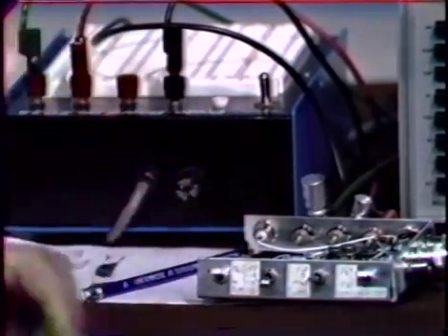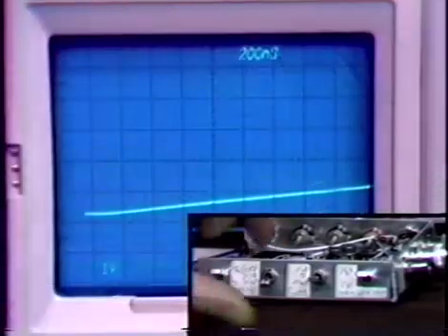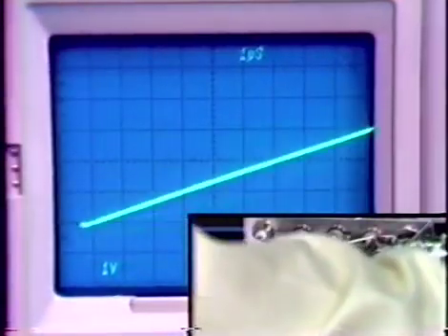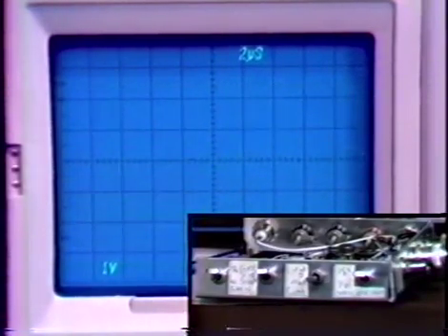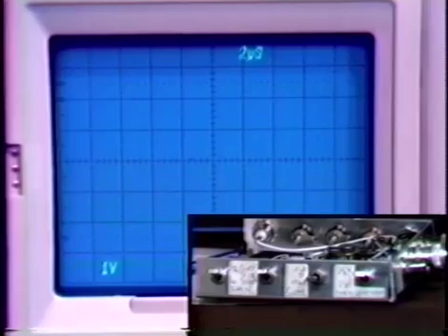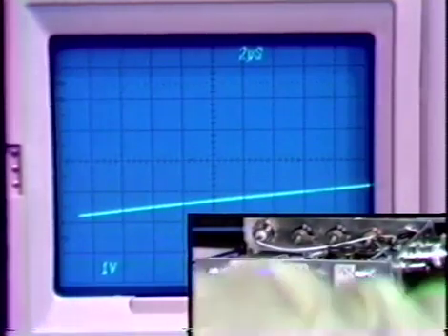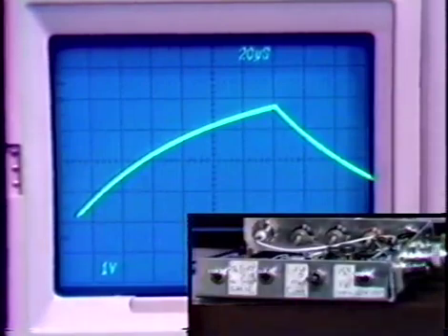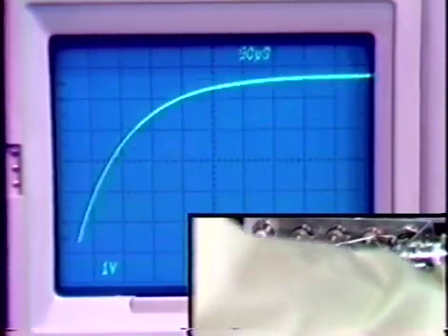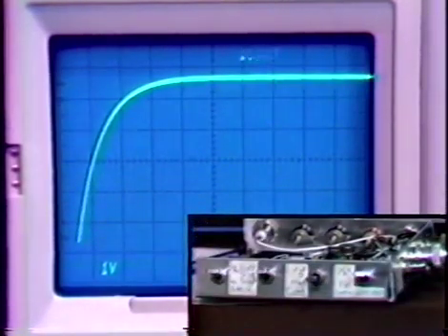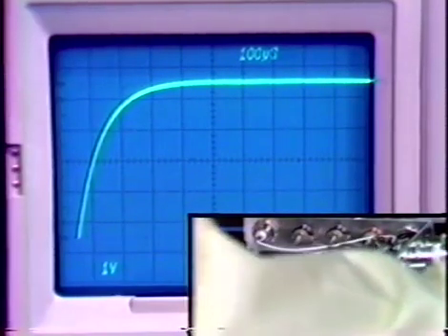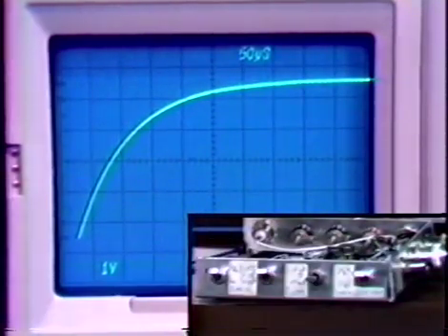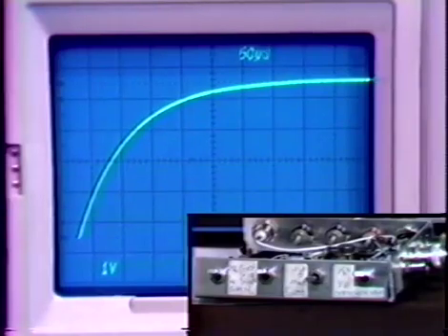And now, let's increase the closed-loop gain to 1,000. We clearly are going very, very slowly. Let's slow down the generator. Things saturate. We've got to put in a smaller signal. We still haven't reached final value. All right. Now we finally have things adjusted so that we can see the rise time with the 20 picofarad capacitor at a closed loop gain of 1,000.